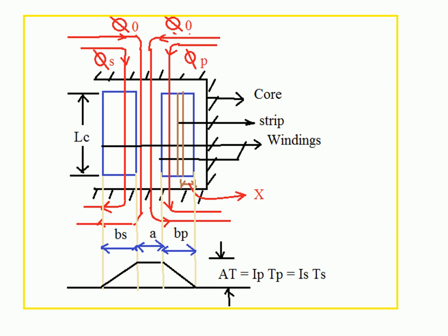Number 2, flux distributes or runs parallel to the height of the winding. That is very important. Then MMF goes on increasing linearly from one end to the other end. That is also important. The MMF for the iron parts is negligible. That is also an important part.